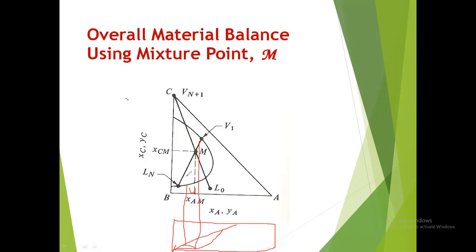If you connect these two, the L sub 1 and the V sub 1 points, it should pass through the bulk phase M. And then you connect this L sub 1 to V sub 2. The same thing: you go down, you turn left, and you have L sub 2. And L sub 2 and V sub 2 will be again another tie line.